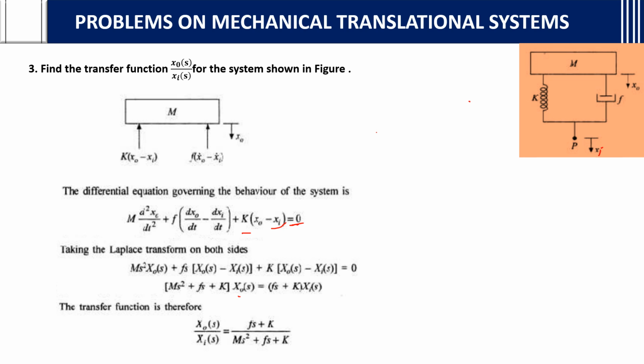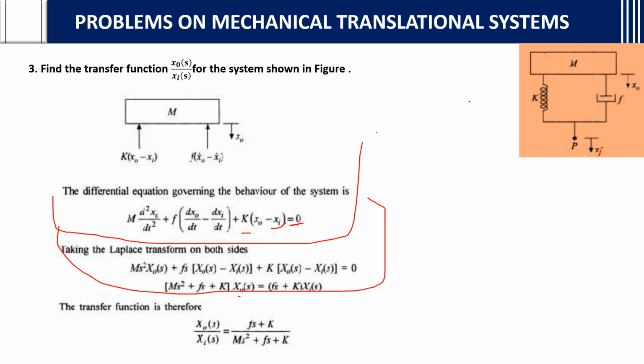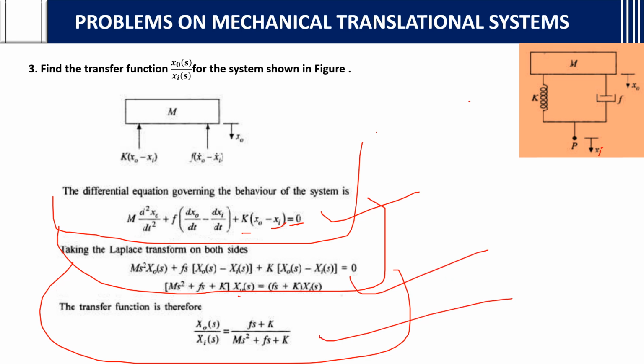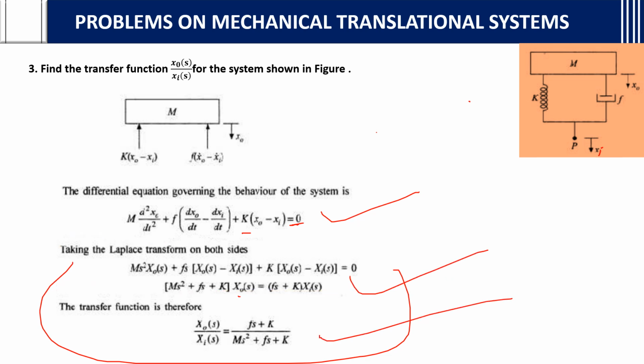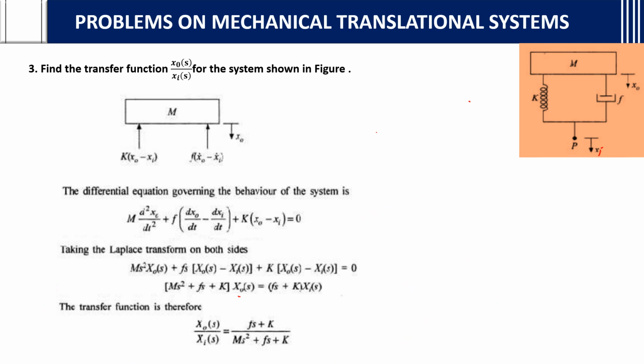transfer function. Or else if they just ask for the differential equation, if you write till here it is enough. Or if they ask for Laplace transform, till here it is enough. But if they ask for transfer function, you need to do this. For differential equation this, for Laplace transform this, and for transfer function this. If the transfer function is asked, first you should write the differential equation, then do the Laplace transform, then the transfer function,